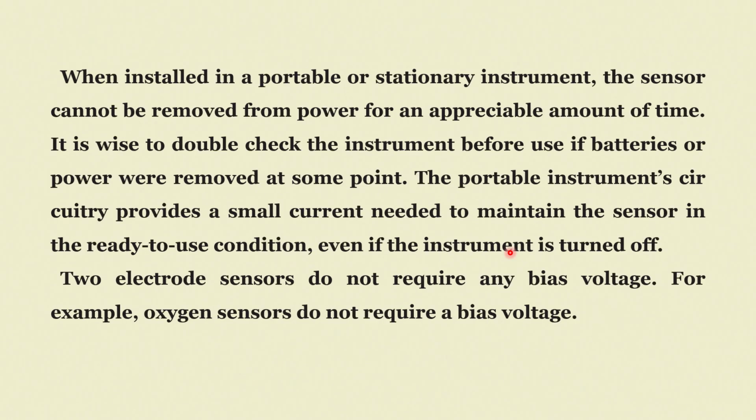When installed in a portable or stationary place, the sensor cannot be removed from the power source for an appreciable amount of time. This is a very common sense statement. Actually, there is nothing technical about this. It is wise to double check the instrument before use if the battery or power was removed at some point. So, the portable instrument's circuitry normally provides a small current needed to maintain the sensor in the ready to use condition.